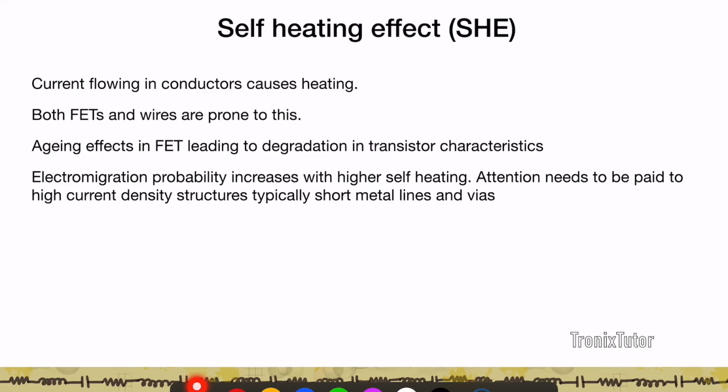For example, if you find a hot spot on the chip and you need to reduce the local temperatures, typically temperature management is done through vias. A very simple way of reducing temperatures is to create these dummy via structures. And what vias do is they are made up of metals, so they're able to conduct heat quickly away from this hotspot. And so there are specific rules associated with via densities which can be employed when you're dealing with self-heating.